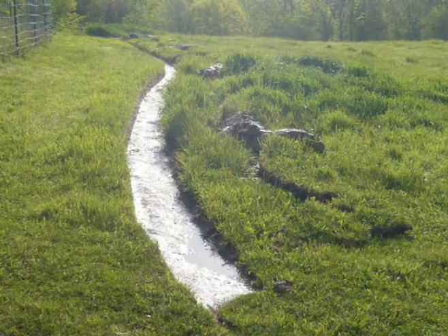So I make what's called a drive-through pond. Take like a pie server and go scoop uphill and then go boom downhill. So you smooth off up here and you fill in down here. And so what ends up happening is your key point pond will fill up, the water will start to flow, then this fills up, then it moves, so it fills up, fills up, fills up. Why I call them drive-throughs is I don't build these with the intention of holding water unless we want to. If you want to hold water year-round, design it that way. This is just designed to catch that surge event.